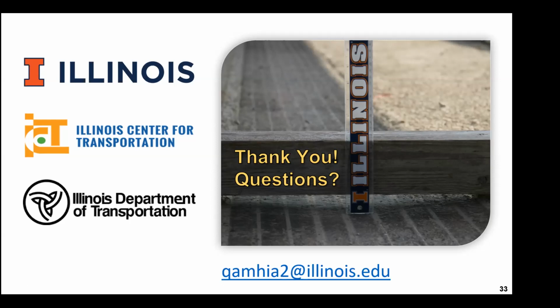I think there is more to understand about how dolomite with up to 12% fines in regular even aggregate gradations can be used with little cement to build the low, medium volume roads, our county roads. That may be a very good alternative. I think there is something that definitely we need to understand better about the good performance of the QB2. And I think this means a lot of savings, significant maybe savings from the point of building local roads, some county roads, if we can make them survive several years.